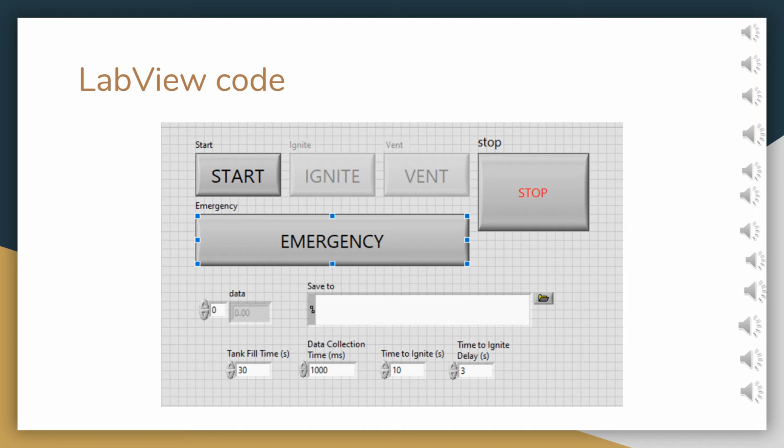The last function on the interface that is located to the left of the Save to File function gives the user a live update of the pressure inside of the chamber at all times to show the user when the chamber is up to specific testing pressures, as well as live updates of the brightness inside of the chamber to indicate when the propellant is ignited and when it is finished. The arrows to the left let the user switch between the pressure channel and the brightness channel.